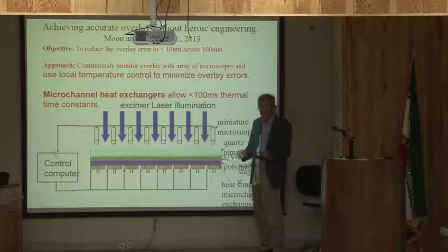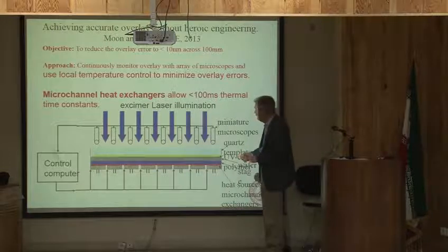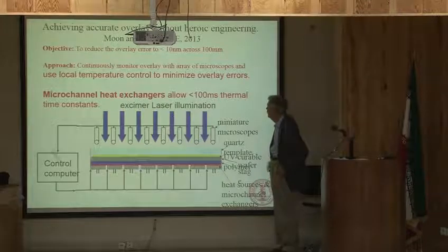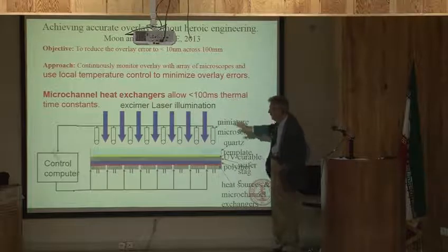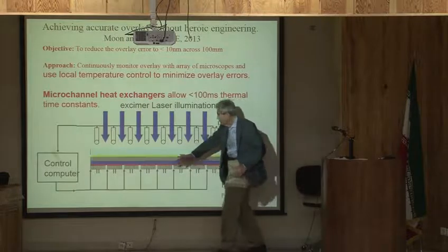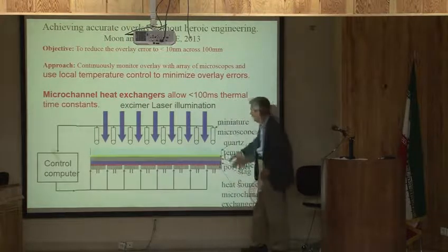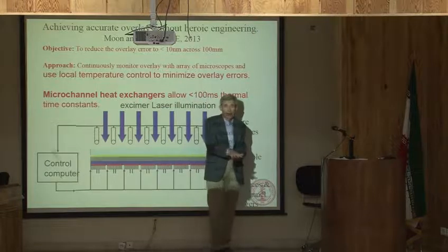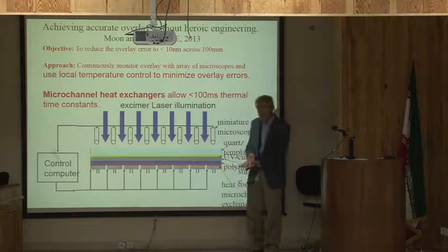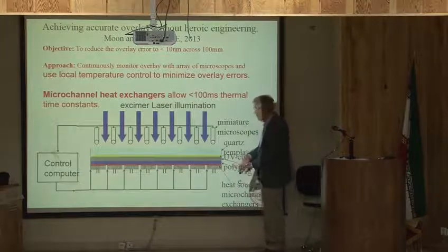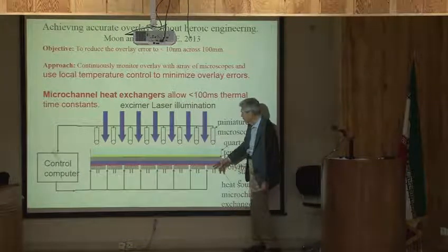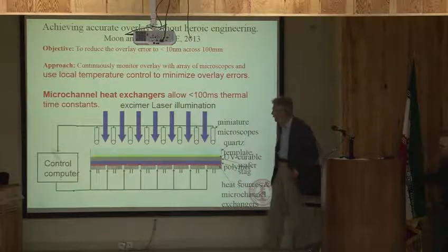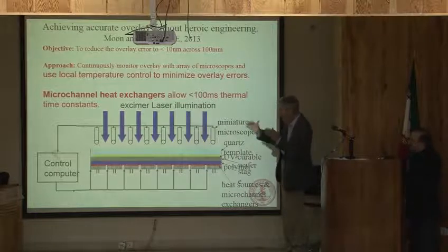That has various applications. And the one I've been trying to investigate, and this is what I'm doing right now, is to see if you can use this technique of locally heating your substrate, monitoring the precision with which you're overlaying two areas, so that we can now get the overlay in the nano imprinting process completely accurate. So we used the technique of Tuckerman and made an 8-inch wafer chuck.